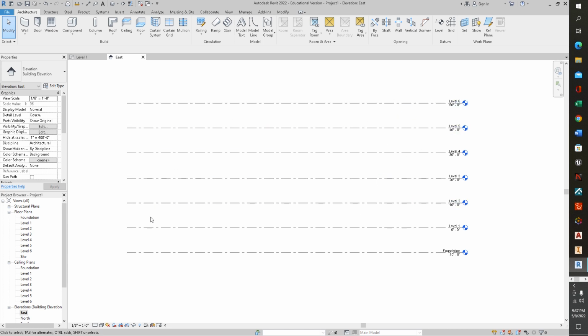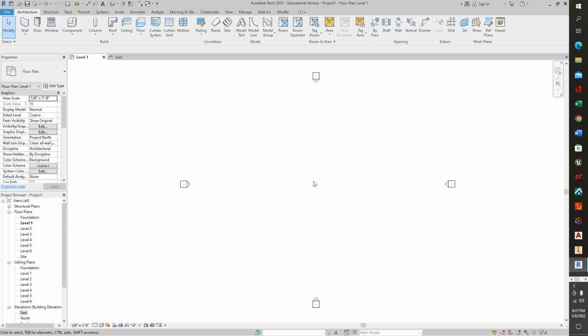And we can then look at our levels on level 1 that we had opened up. It doesn't show us anything yet, but we'll put in the grid lines for this as well. So what we have to do to get the grid lines going, which I wouldn't mind starting up in level 2, is double click on level 2 in the project browser, as that will give us other options that we can load in later. You'll see that makes sense to do this.